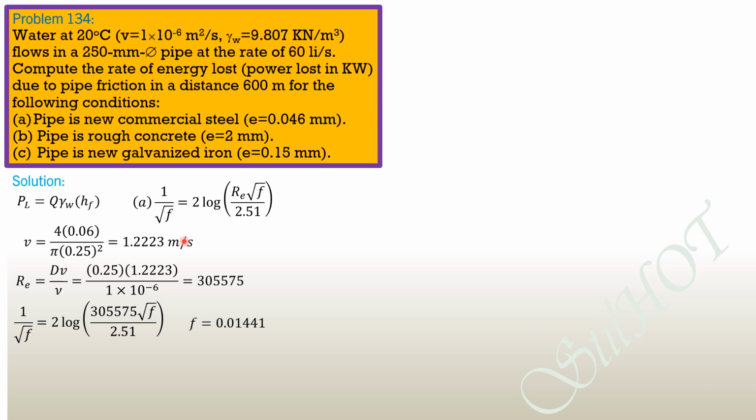Then the thickness of the viscous sublayer is 14.14 times diameter over Reynolds number square root of f, or 14.14 times kinematic viscosity over quantity mean velocity square root of f. So we'll use the other formula, 14.14 diameter over Reynolds number square root of f, where this is in mm if the diameter is set to mm also.